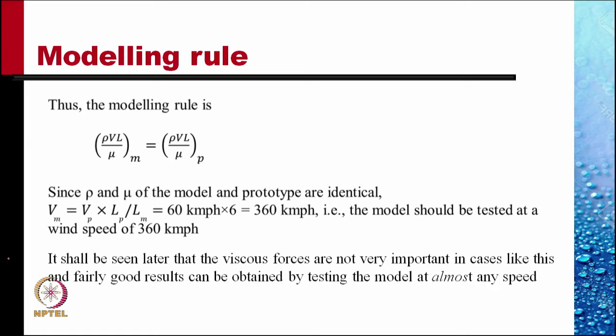It shall be seen later that the viscous forces are not very important in these cases. When the Reynolds numbers are very high and the body is blunt or bluff, as an automobile typically is, the viscous forces are not very important for drag modeling. And fairly good results can be obtained by testing the model at almost any speed. Anyway, we'll come to that a little later.